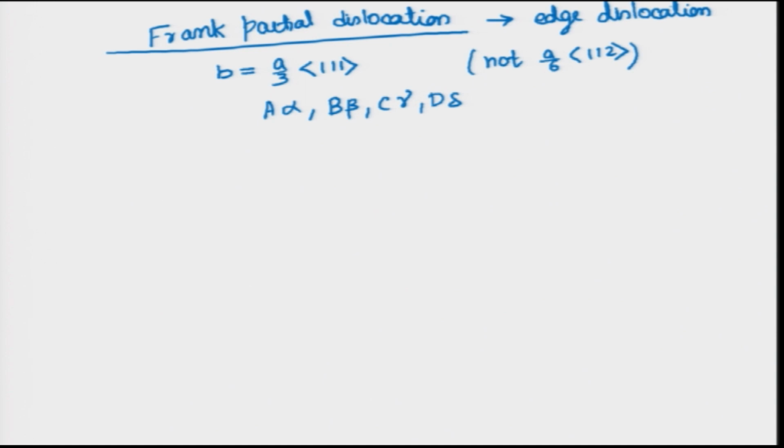Now, another thing is that you will note that this does not, I will call it BF to differentiate, BF does not lie in {111}. So, this is a direction <111>, so it will always be normal to one of the {111} planes, and the {111} plane normal does not lie on any of the {111} planes, and therefore, BF also does not lie on any of the {111} planes.